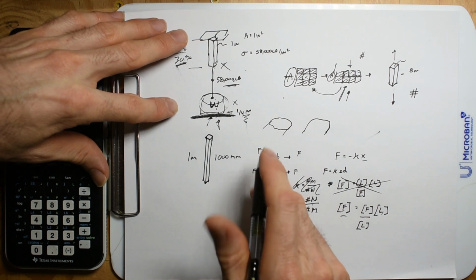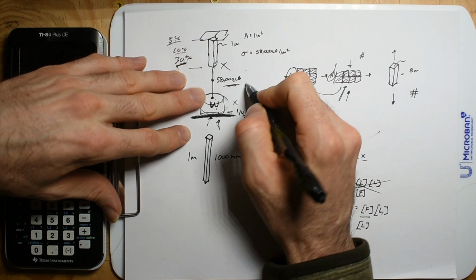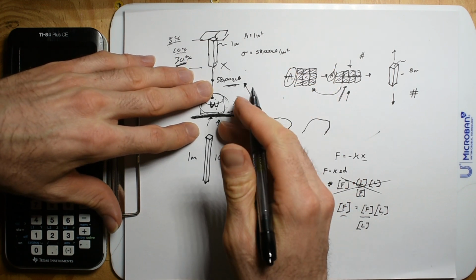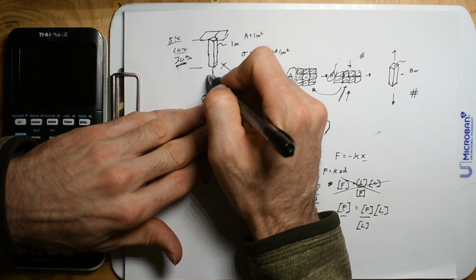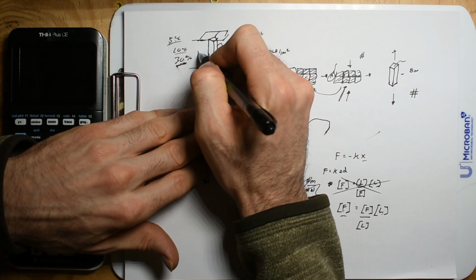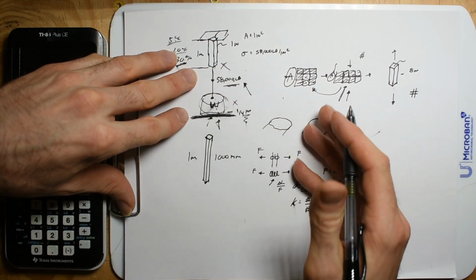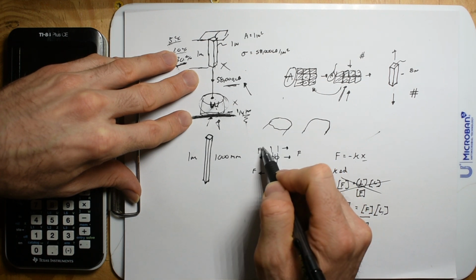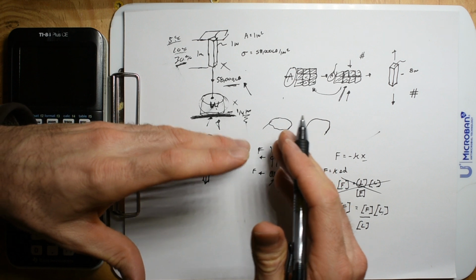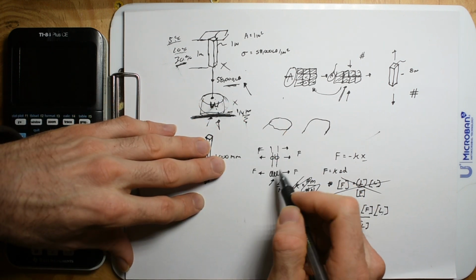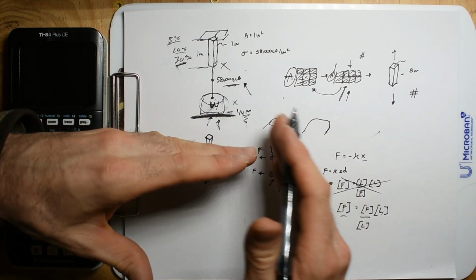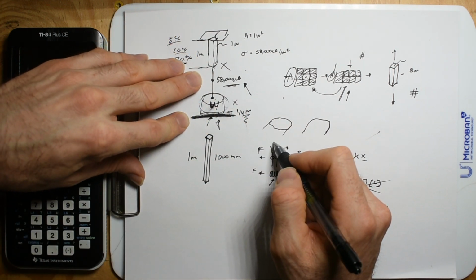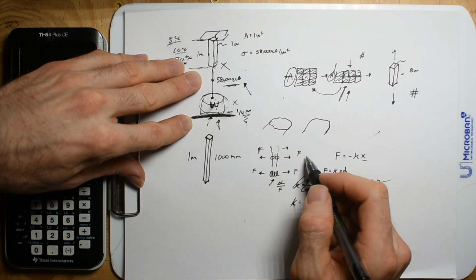What happens is that you can get up to 58,000 pounds, then take the weight away, and this 1 meter steel bar will go exactly back to 1 meter. So that's the other property of material mechanics. If things are elastic, you can put a force on them within that elastic range, just like a spring, and then let go of the force. This whole thing goes back to its original dimension. And it's actually remarkable that materials behave that way.